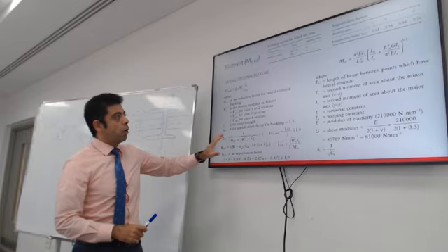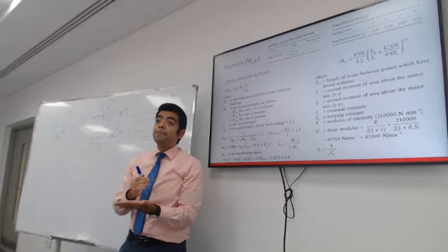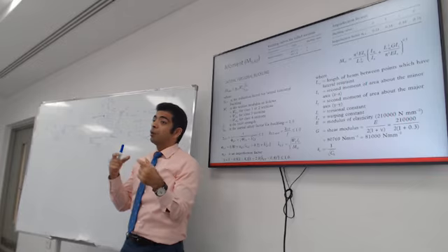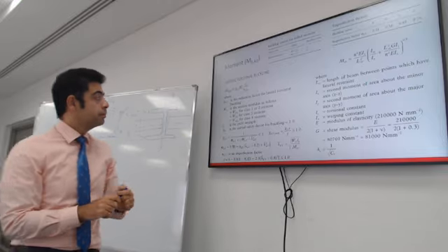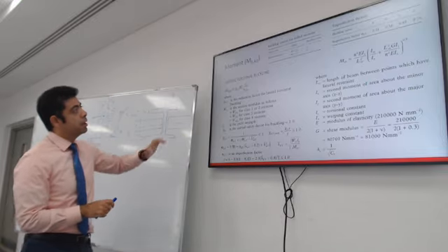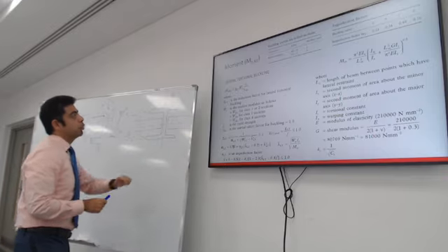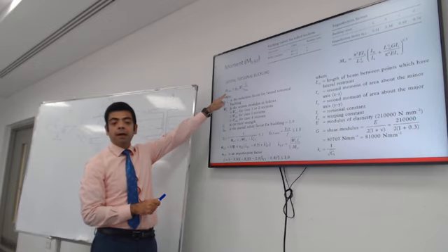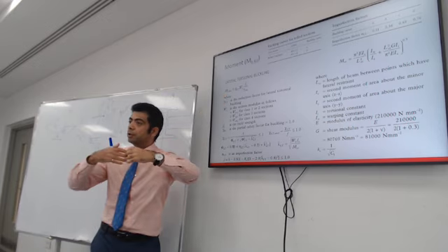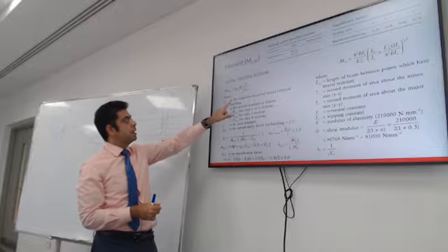All right, so this is all something we covered when we designed beam under moment with lateral torsion buckling. We will need this for the example. So the notes will tell you in order to get the moment capacity considering the lateral torsion buckling, you need to get 4 things pretty much.